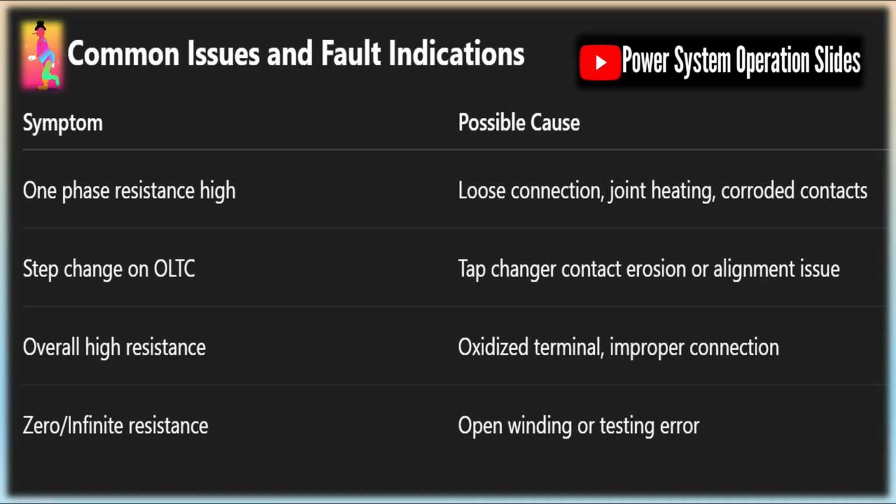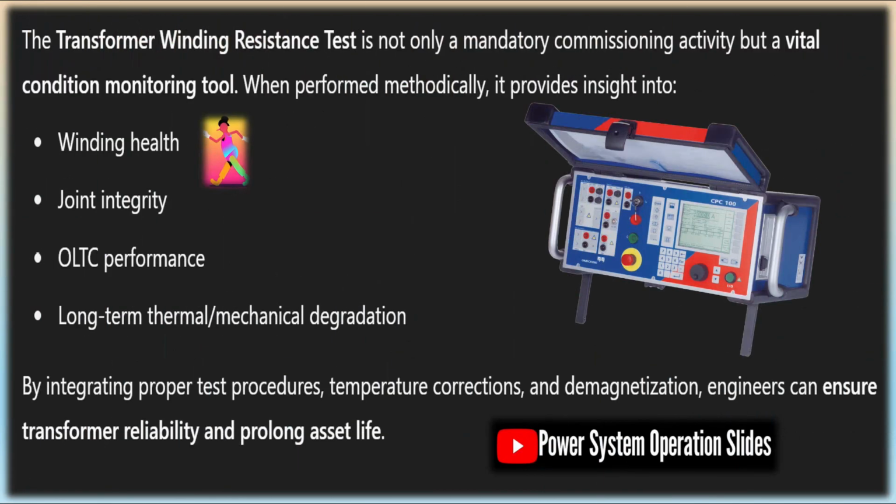Once the voltage reading has settled, the test instrument calculates the resistance by applying the relationship between voltage and current. Accurate results depend on calibration of the measurement device and careful attention to the contact quality at the test connections. Consistency in procedure is essential to establish reliable data for trend analysis.